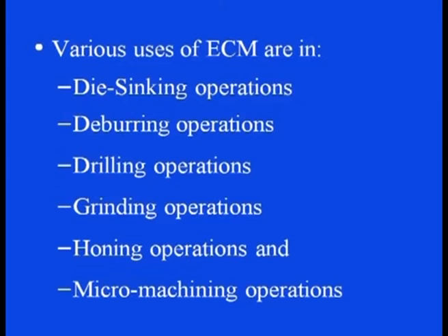Now, let us see the uses of this ECM process, in what are the different applications where this can be effectively used: for die sinking operations, for example, for deburring operations, for drilling operations, for grinding operations, for honing operations, for micro machining operations. This process is found to be very effective.